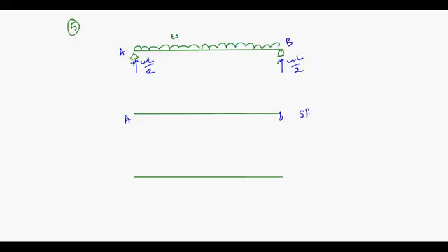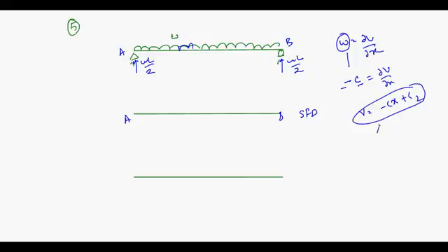Now when you are drawing shear force diagram, you know W is equal to dv/dx. Now W is constant, negative, so I am writing it minus C. C is a constant and negative sign because your loading is having downward direction, isn't it? So minus C, so your shear force will be minus Cx plus C2. You don't have to solve and get this equation, there is no need. You just get the idea that it is a straight line with negative slope. Is it okay? And the value of slope is W.